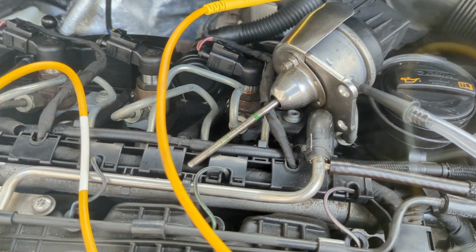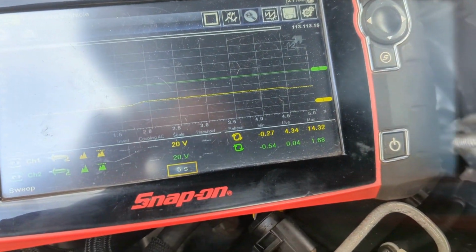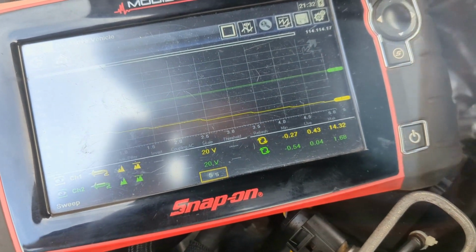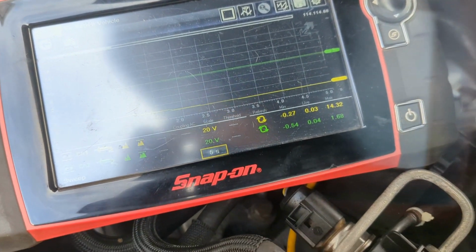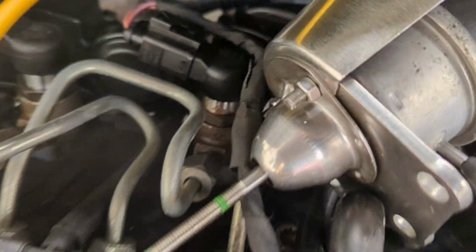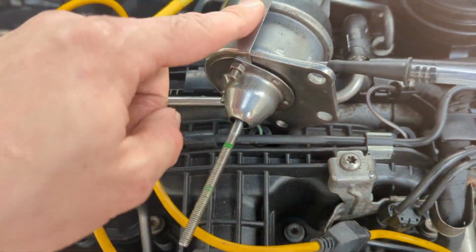Apply vacuum, that moves outwards with vacuum, and we'll watch this voltage. Dropped way low. So either this turbo, the vane's starting to stick, these nuts, or this actuator isn't adjusted properly, like locking them off and see what happens, or this is just no good. This one seems better, I might have to put this one on.